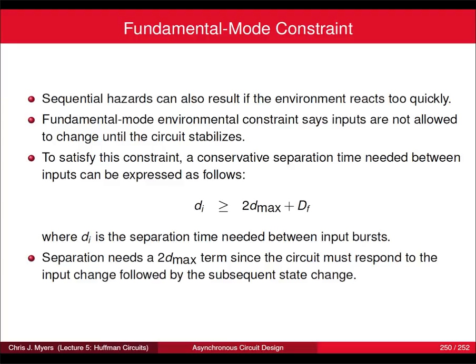Multi-level logic synthesis and TechMap are changed only modestly from synchronous design. And the other very nice thing is if you give me a legal burst mode state diagram with maximal set property, I can promise you we can get a circuit for you. These are all very nice properties. The one negative property is cycle time, because you have to provide your inputs in these input bursts in order to be sure that you don't have hazards, to meet all of your timing constraints.